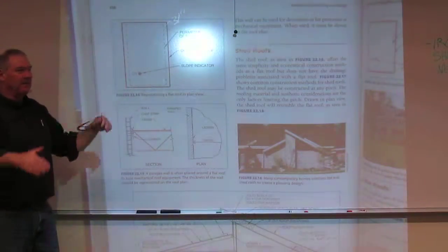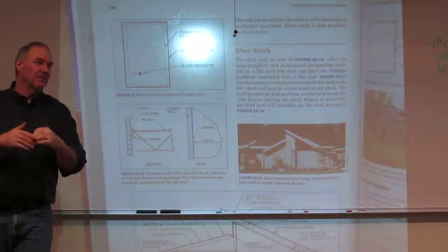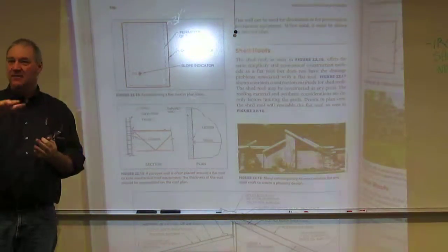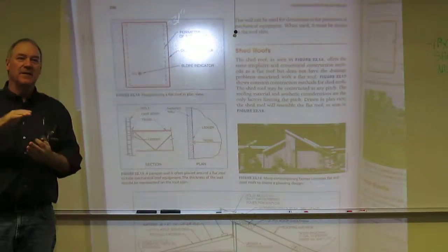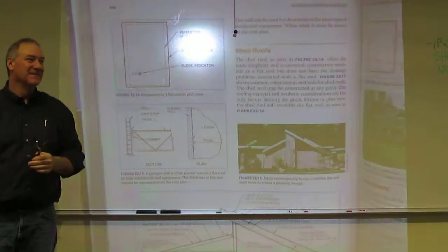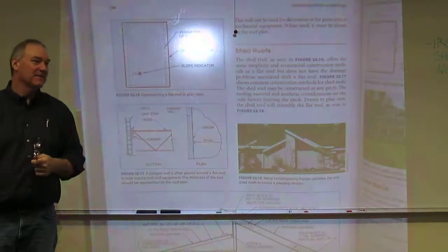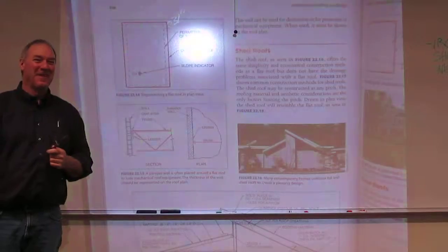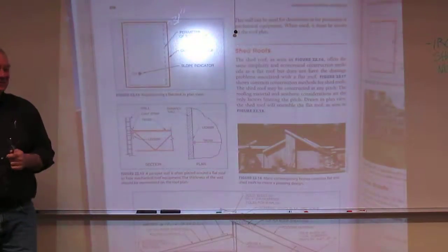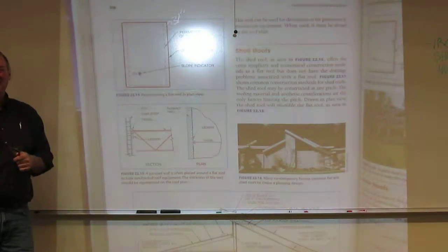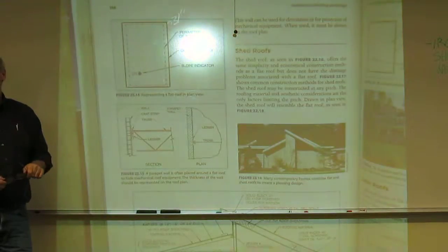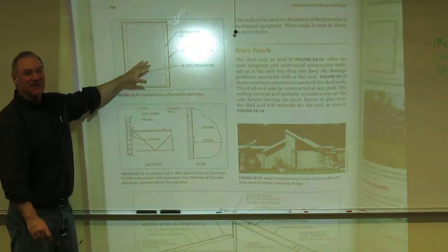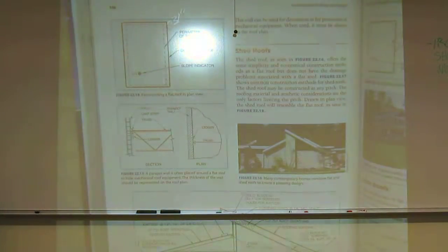So typically there will be a bunch of layers of what we call bituminous, or in essence tar. And then on top of that, you're going to see a bunch of gravel placed. The gravel is only there so you can walk across it. It's not really there for anything else. On a hot day, you ever tried walking across the tar? Well, you leave your shoes behind, right? Flip-flop first. And that's why we put gravel over it. So if you go on most commercial buildings, what you're going to see is a big patch of gravel. Underneath that is a waterproof layer.